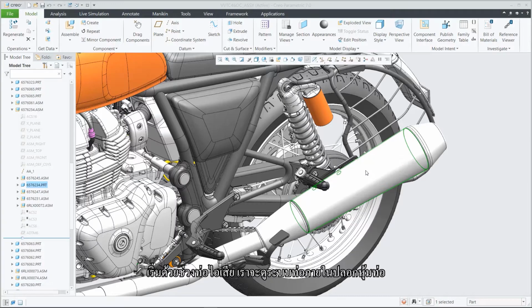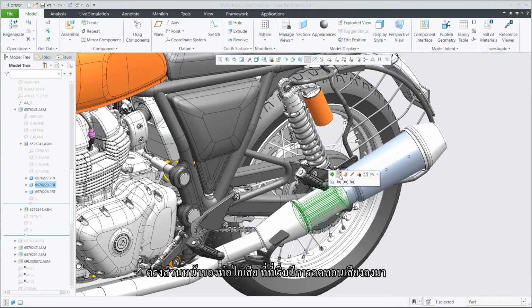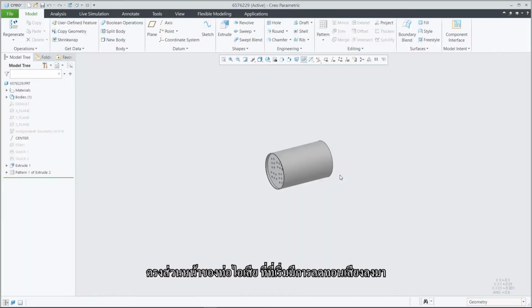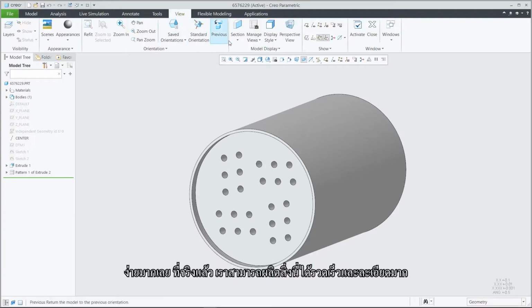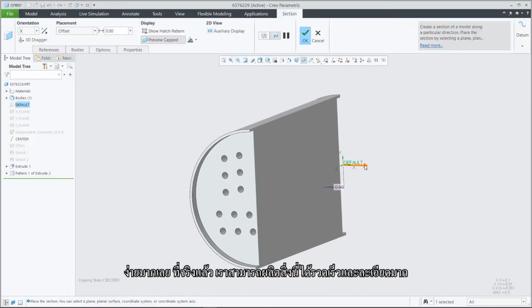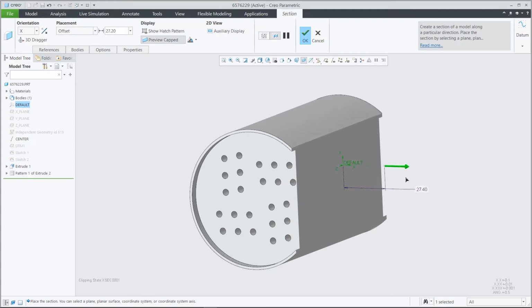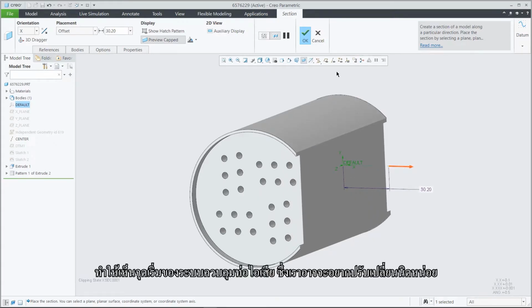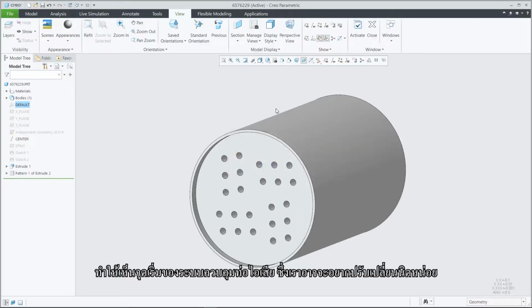Let me go ahead and hide the casing here. So the front section of this muffler is actually where the sound attenuation starts, and the current design is basically just holes, if you will. Very simple, but the idea is we can manufacture this very quickly and in great detail. Let me go ahead and cut away on this part. You can see what I'm talking about here. So that provides the start of the exhaust control there, but maybe we want to get something different here.